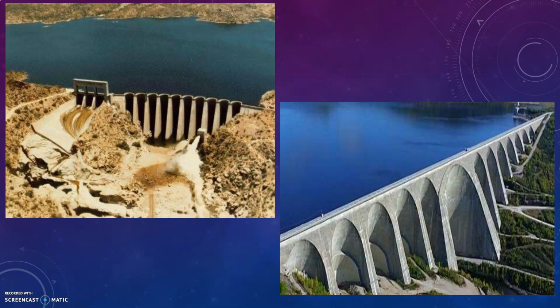However, in the case of buttress dam, further rising of the height is possible and convenient by extending buttress and slab. Consequently, buttress dams are used where a future increase in reservoir capacity is contemplated. And also powerhouses and water treatment plants can be housed in between buttresses, thus saving some cost of construction.